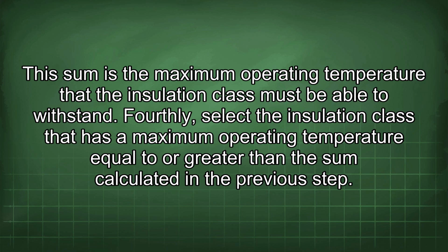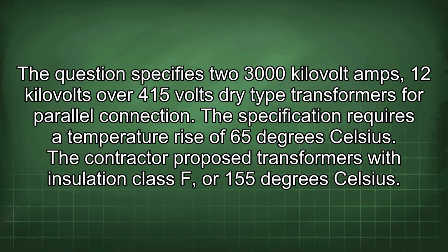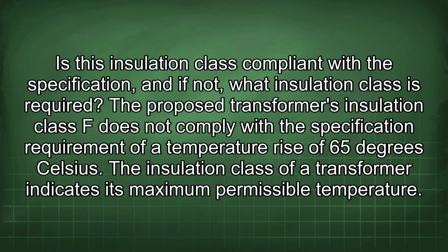The question specifies two 3000 kVA, 12 kV over 415 volts dry-type transformers for parallel connection. The specification requires a temperature rise of 65 degrees Celsius. The contractor proposed transformers with insulation class F, or 155 degrees Celsius. Is this insulation class compliant with the specification, and if not, what insulation class is required?